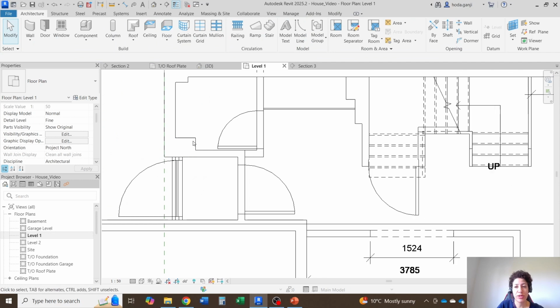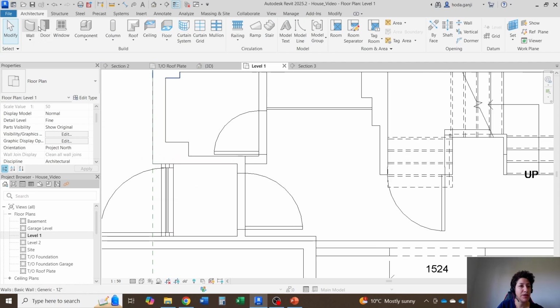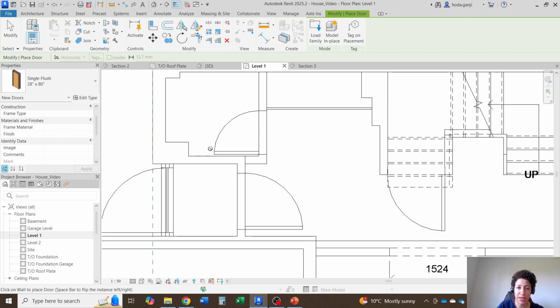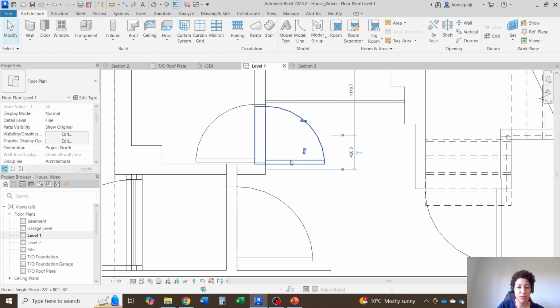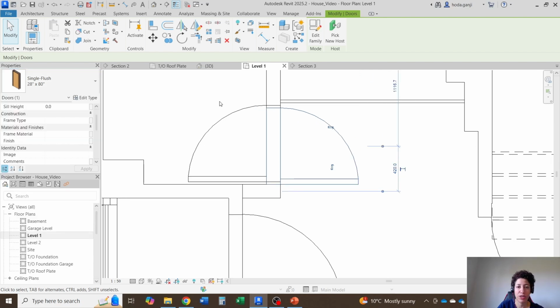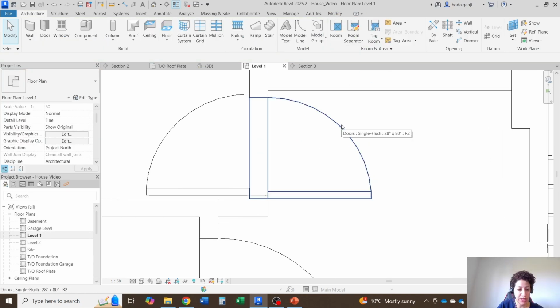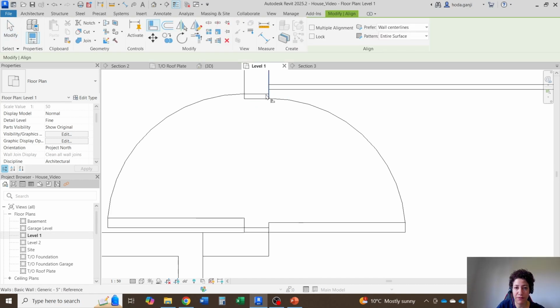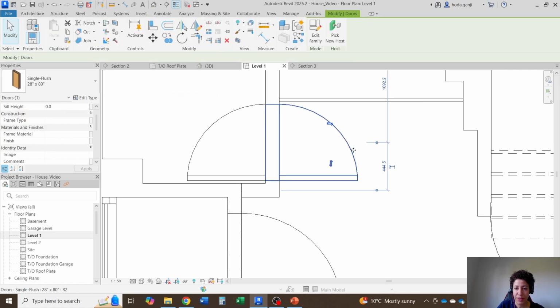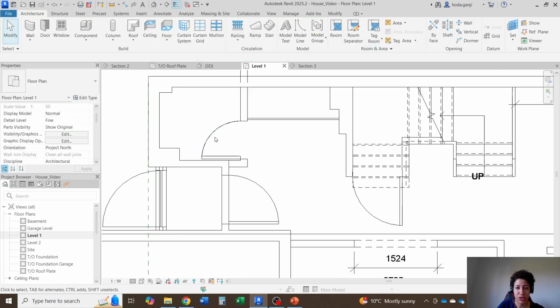Keep adding your interior walls, doors. Like if I want to add this door, I need to switch to one of my doors. I guess this is 28 inches. I can hover the mouse around here, put this here. If you had by mistake chosen a wrong door, you can always come back and go with the correct one. And I want to use AL again, AL, select the reference and then select the edge of the family, and feel free to select the door, use these flip icons to adjust it in the right locations.